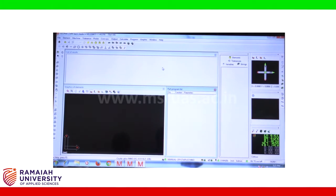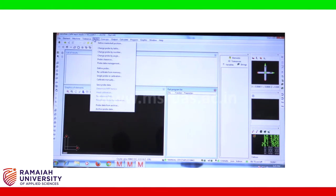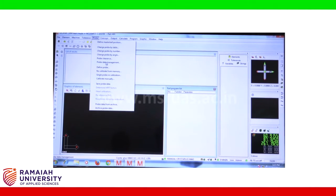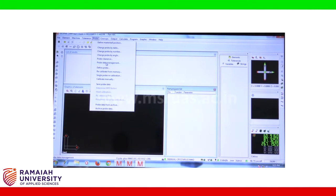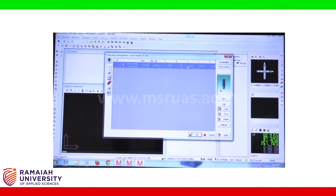The next step is defining the probe. So you can see the probe menu falling down. You can see the different options. Then I am going to the probe data management. You can see the initial probe, the diameter of the probe, the difference, the A axis, B axis, X, Y, Z axis.